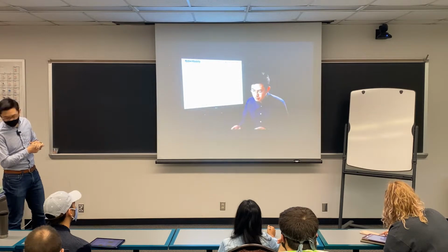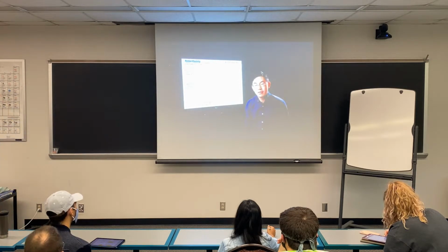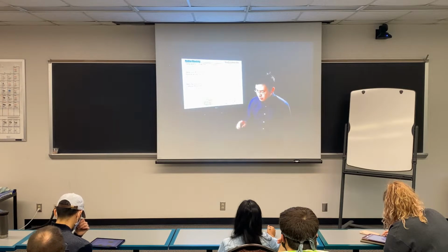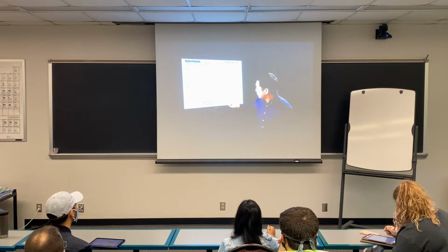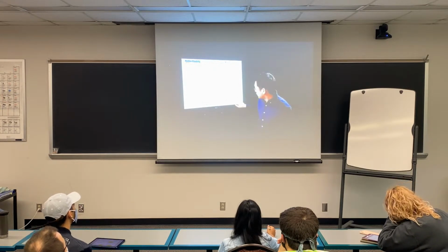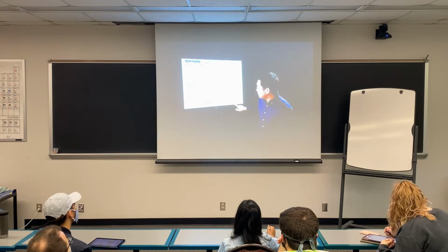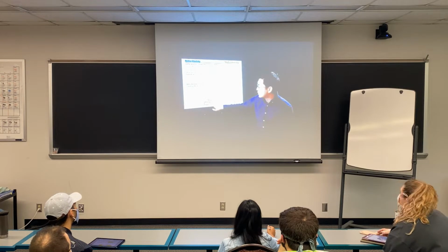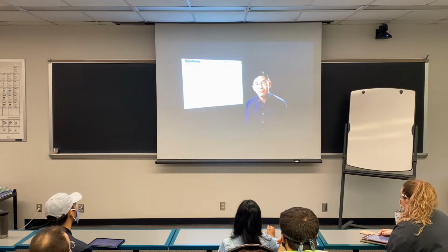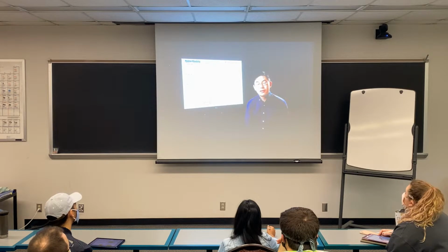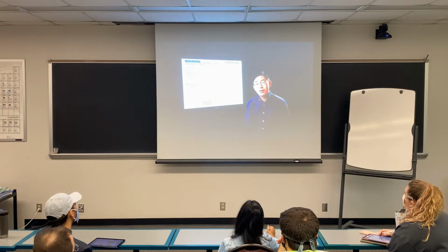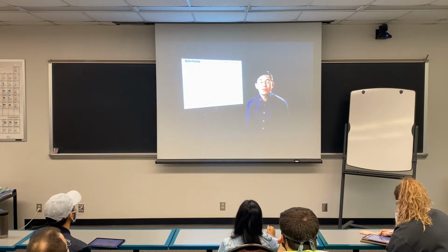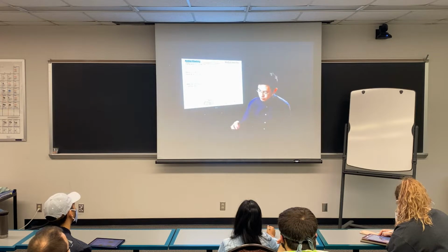So this is where we were left, and this is an important part of the lecture where we discuss what G, the modulus, depends on: the cross-link molecular weight Mx, or you can understand this as the number of cross-link points within a given volume. In other words, the theory nicely describes that if the temperature increases or cross-link density increases, your modulus, or the strands of the rubber, get stronger.